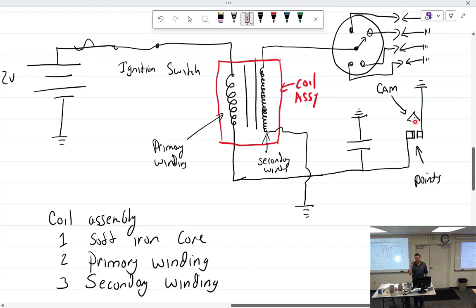Well, you have to fire it at the exact right time, because the piston is going to be at the right place. So you got to make sure that's timing the engine, or in our case, you have to time the magneto to fire at an exact spot. That exact spot has to be where the piston is. We'll get more into that later.